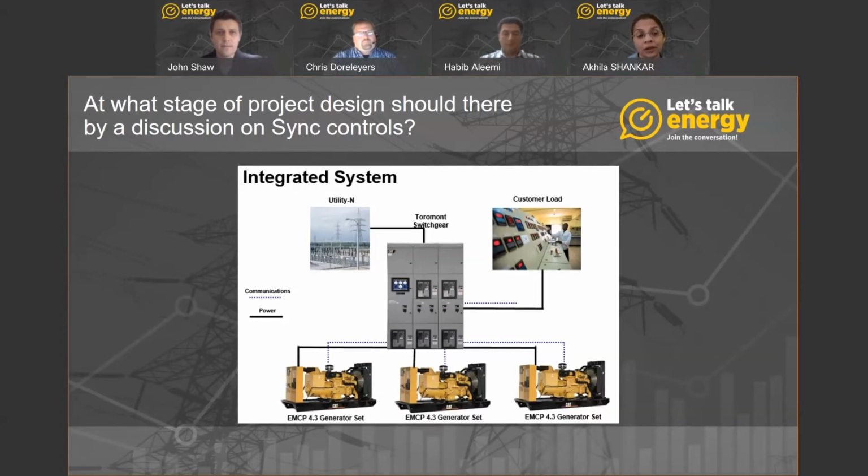This solution allows for multiple generator paralleling in island mode, as well as paralleling to multiple utilities or multiple tie breakers as well. And system level data can be displayed on touchscreen system HMIs. In short, we can offer the most flexible and customizable design that is supplier agnostic, meaning we can use any breaker manufacturer in the switchgear and any PLC that the customer desires.